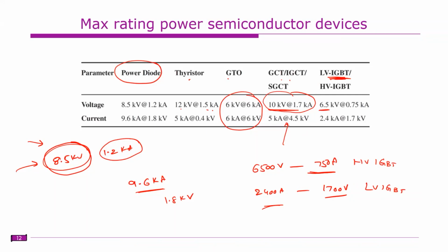Usually if you try to increase the blocking voltage of the device, the on-state voltage drop will increase. If it is carrying the full amount of current, the switching losses will be increased. That's why every time you want to increase the voltage, they use a different manufacturing process.